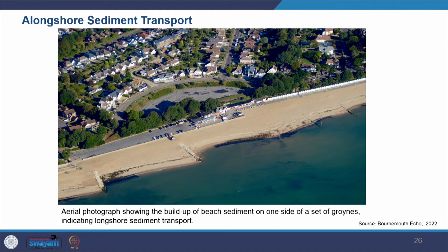You need to take several parameters into consideration, and you can take observations of buildup of sediments, which you can see at cross shore structures and the alongshore growth of spits. We are going to see what spits means. But by observation of the shoreline, you can also understand in which direction the transportation is happening. That allows you to understand the real characteristic of this place.